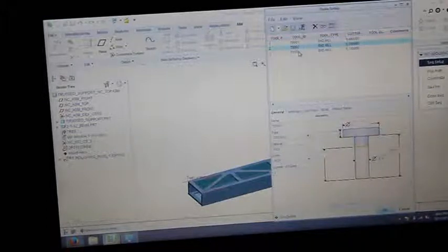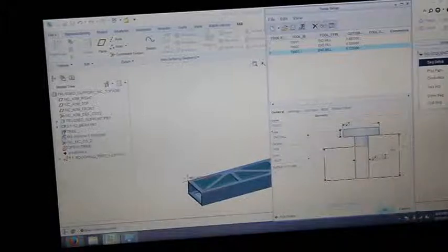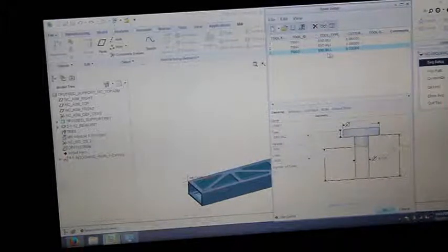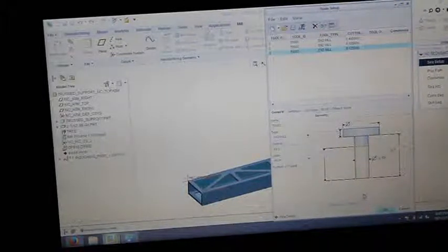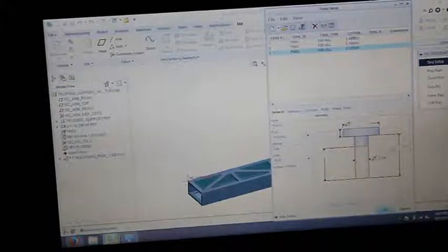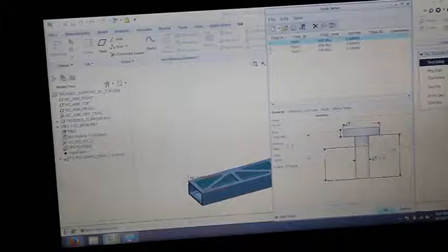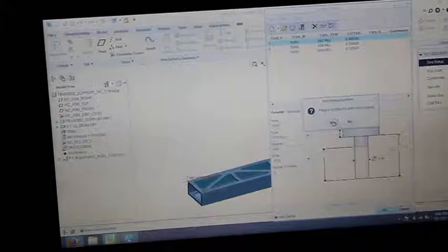We've already defined 3 tools that we can use. We defined their diameters, what kind of tool they are, and their numbers and IDs. This is where you can specify the type of the tool, and in this case it's selecting tool 3, but we're actually using tool 1 for this operation. Tool 1 has a diameter of 0.48 inches and a number of other useful information: material, high-speed steel, inches, 2 flutes, some fairly straightforward information. So we can cancel on that actually.